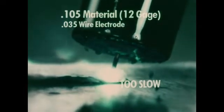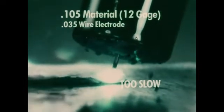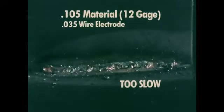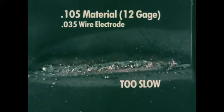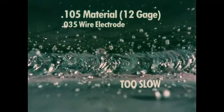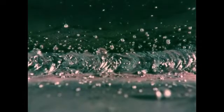The arc action is very irregular. Spatter is present. The bead indicates that the electrode has been melted, but is not properly fused to the base metal. The bead is too small because of the lack of filler wire.